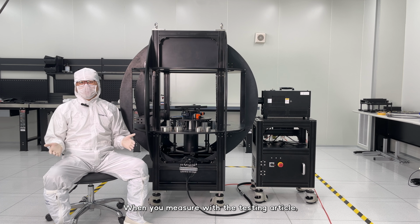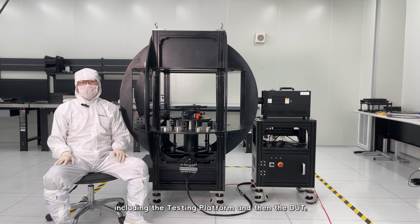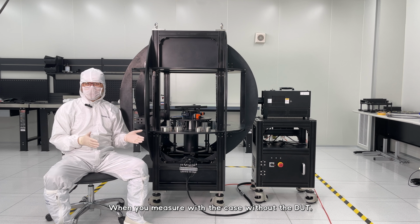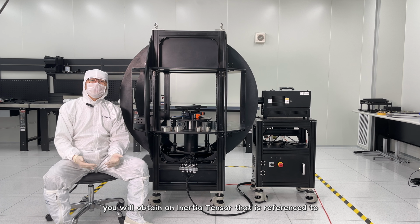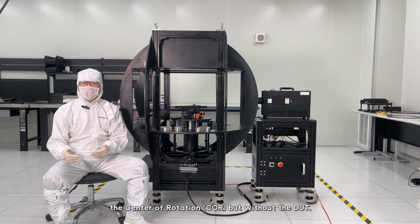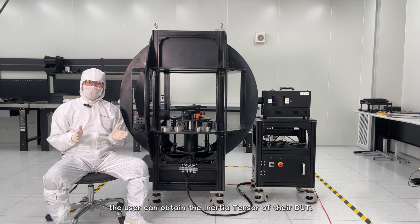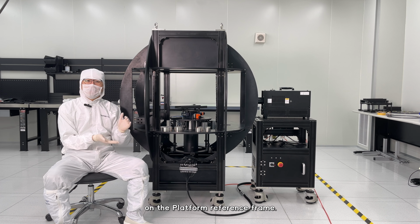When you measure with the testing article, the inertia tensor you obtain is the inertia tensor including the testing platform and the DUT, and referenced to the center of rotation. When you measure with the case without a DUT, you will obtain an inertia tensor that is referenced to the center of rotation but without the DUT. Comparing these two results, the user can obtain the inertia tensor of their DUT in the platform reference frame.